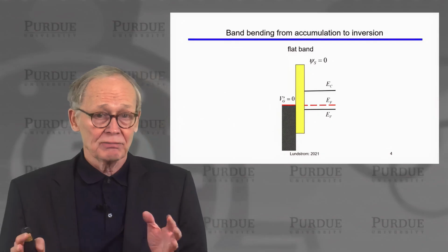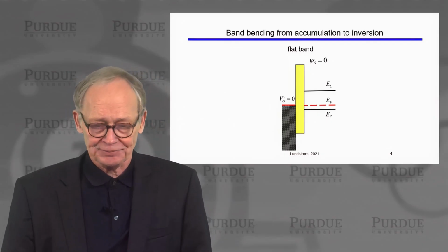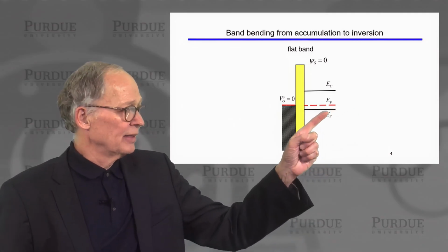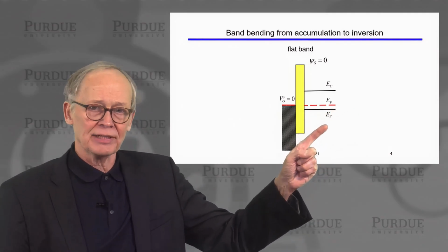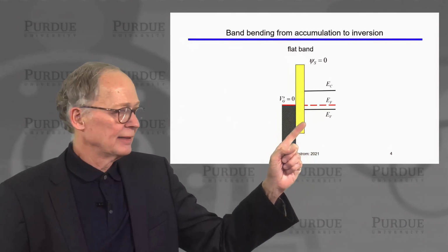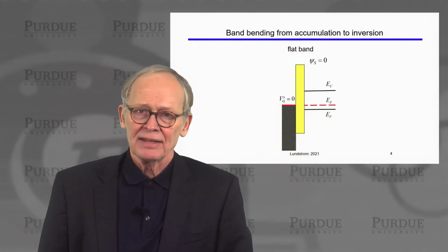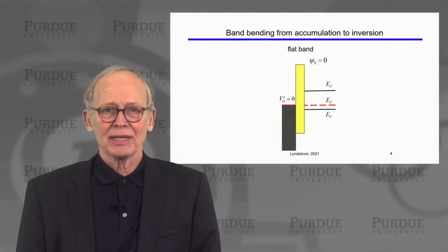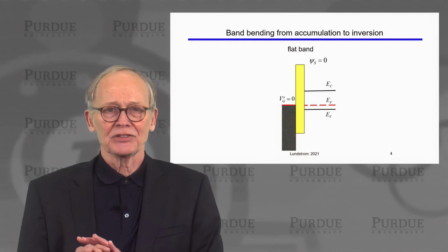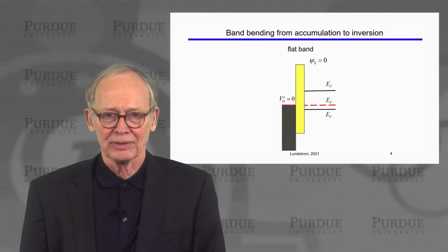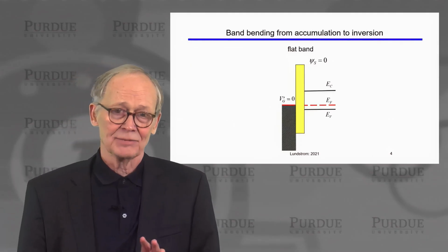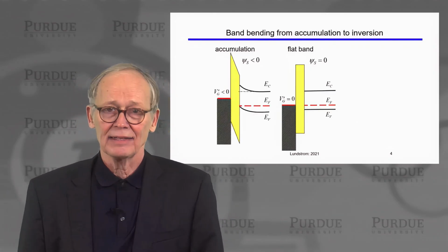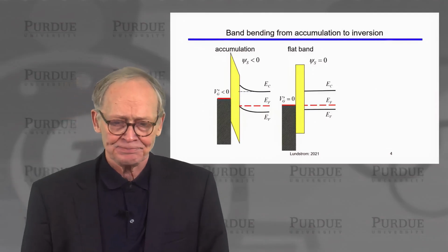Okay, so first thing was one-dimensional electrostatics. So here we have an MOS system. We have a semiconductor, a p-type that we assume is infinitely thick. We have a thin oxide, and we have a metal electrode. The VG prime means that this is an ideal case where the Fermi level in the metal and the Fermi level in the semiconductor just happen to line up at 0 volts applied to the gate. All right, that rarely occurs. But conceptually, it's a simplifying way to deduce what happens, and we can fix it up later.